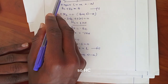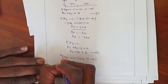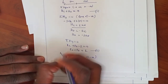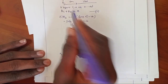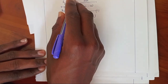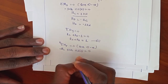HC rotates about point E in anti-clockwise direction, so it will be negative; its perpendicular distance is 5, so it will be negative 5 HC. LC rotates about point E in clockwise direction, so it will be positive 5 LC. The unit load rotates about point E in clockwise direction, so it will be 1 times its perpendicular distance 5, equal to 0.